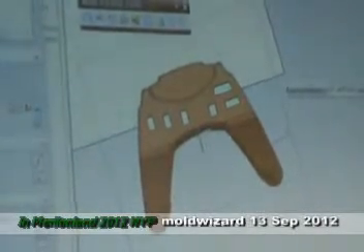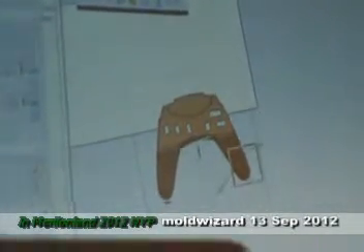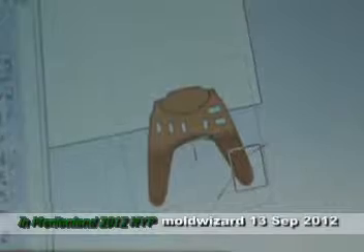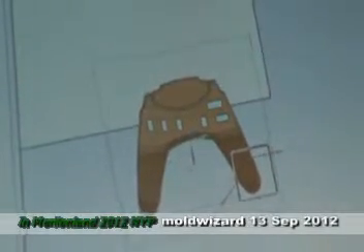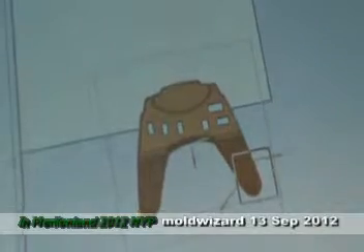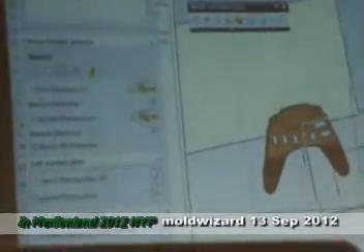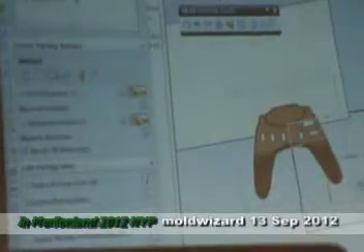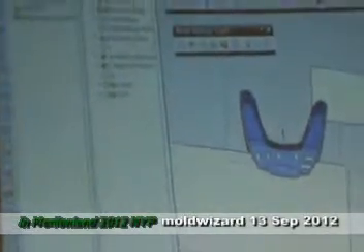Can you extrude in this direction? Okay, so we go to bounded plane, and for the first arrow, I want to follow Y. And for the other arrow, I want to follow X. Drag and enlarge the surface to cover up this part. So accept. Check. It's okay so far.